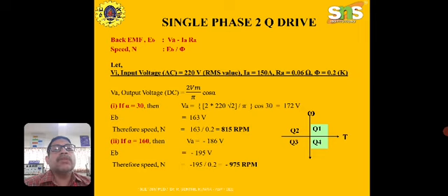With this, we understand that for two quadrant operation, for this circuit, forward motoring and reverse motoring come into picture for a motor. There is no braking since quadrant 2 and quadrant 3 are absent here. Only motoring, forward and reverse motoring operation.